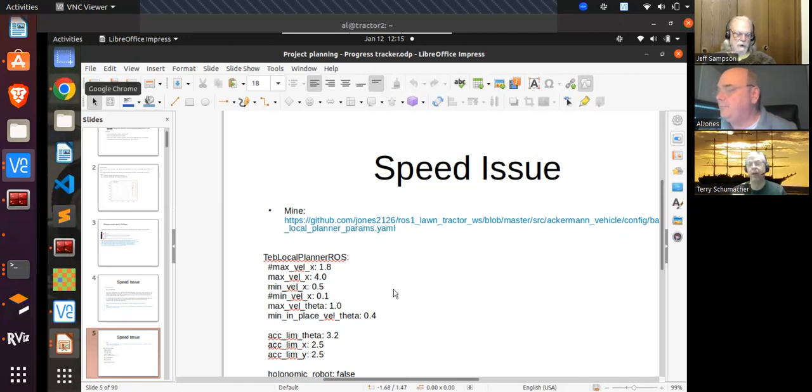I'm kind of jumping ahead to setting my PID, and I'm wondering what units to set for a PID. Is it revolutions per second? Is it distance traveled per second? In ROS, as a standard, all velocities are represented in meters per second. All rotational velocities are radians per second. Angles are in radians and distances in meters. So it's just combinations of those.